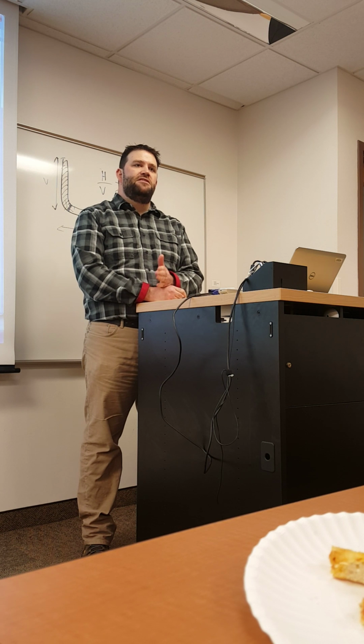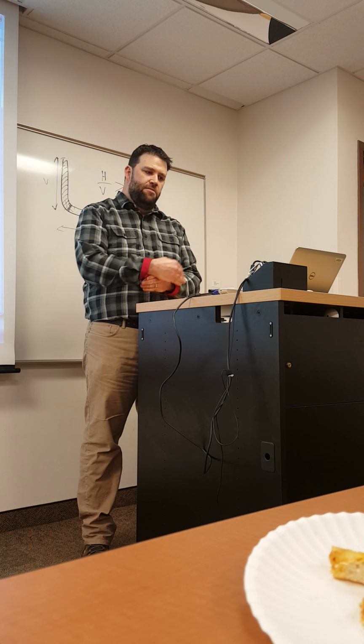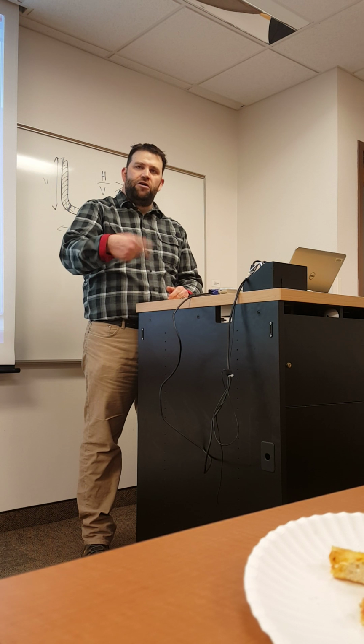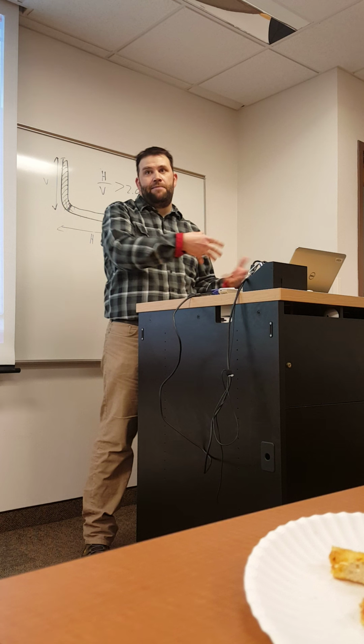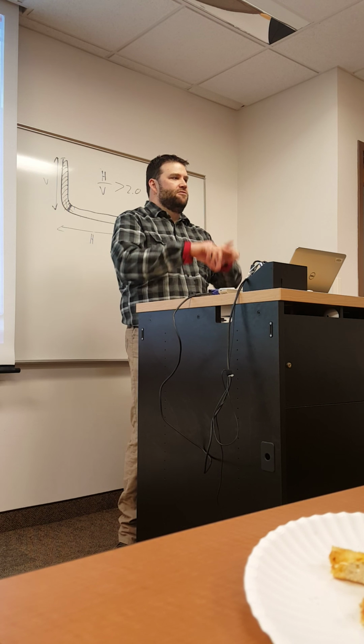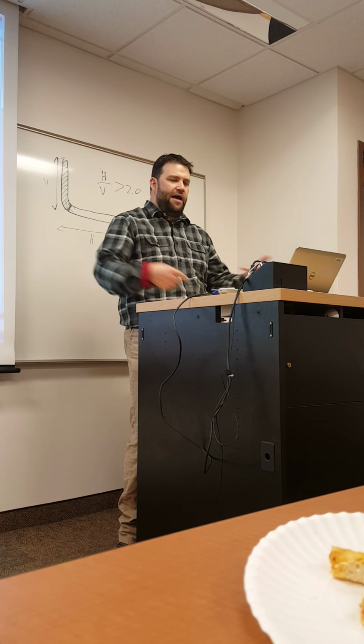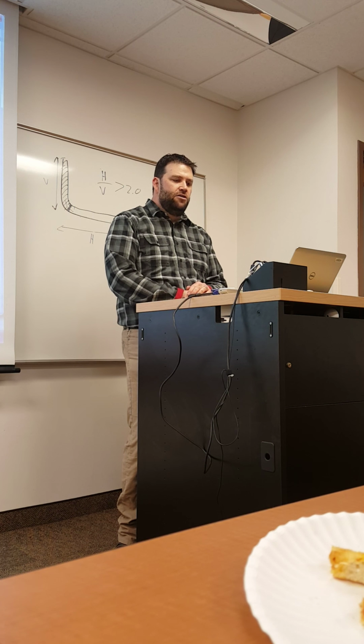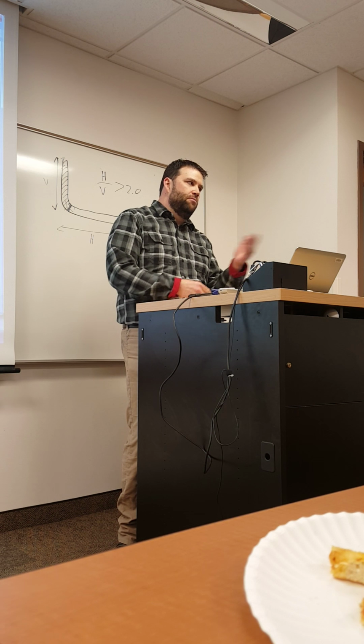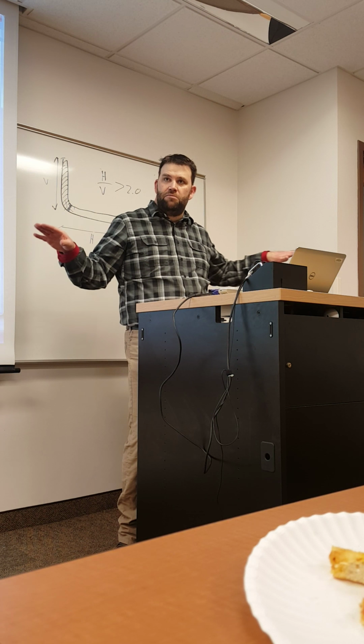But one of the major disadvantages of that is that the bigger the bend setting, the lower that you're allowed to rotate for fear of fatigue damaging the motor. With a big bend setting, there's a lot of bending stress in the motor, and so with higher revolutions, you fail it faster. So what tends to happen with a motor in the hole is the directional drillers say, hey,